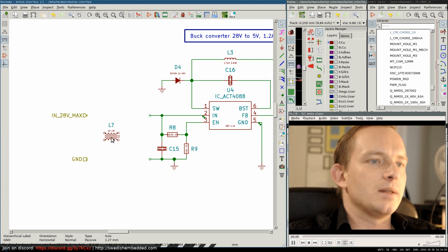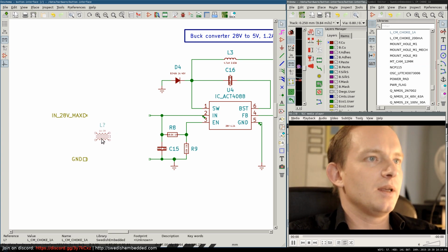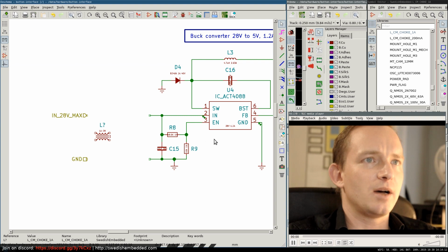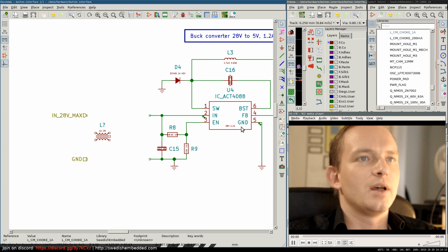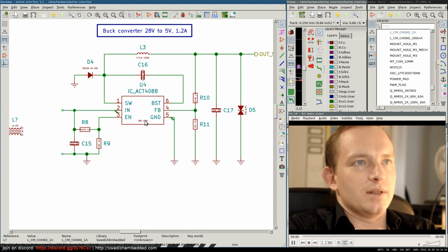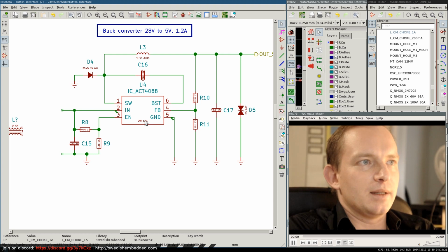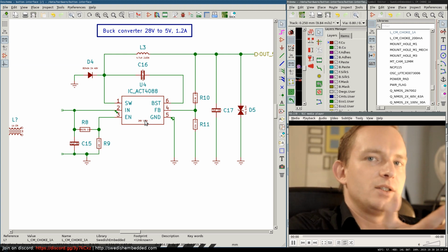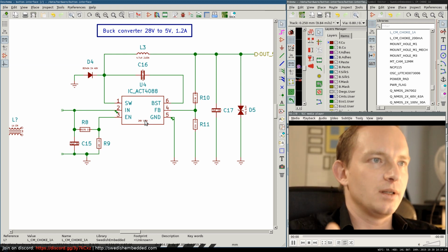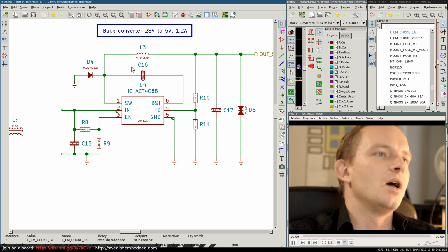And we're going to be keeping earth separate from the circuit ground. So on the circuit, we'll have ground that spans all of the ground pads and all the ICs, but that's going to be ground that is local to the circuit, and then that ground is going to connect to the chassis, which will connect to earth, in theory.